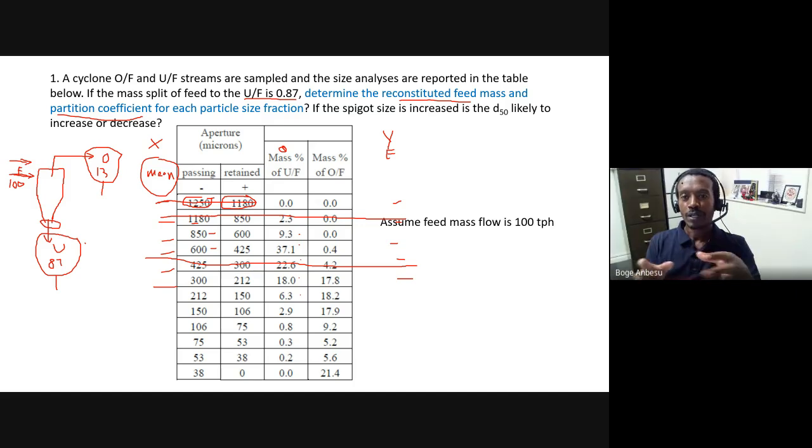I don't know what part you heard, but what I was saying is that here in Australia, we have very high TDS water. Whatever we dig from the ground is very high in TDS. And the problem is not high TDS or low TDS. The issue in a cyclone, especially, is if you have coarse particles suspended in the water. You could have low TDS water with coarse particles in it, or high TDS water with very fine particles in it. The one that's low TDS but has coarse particles will be a problem.